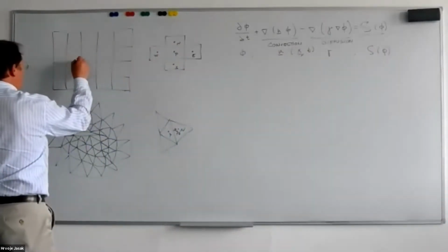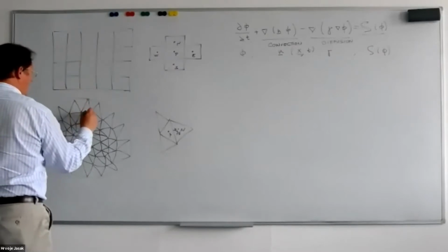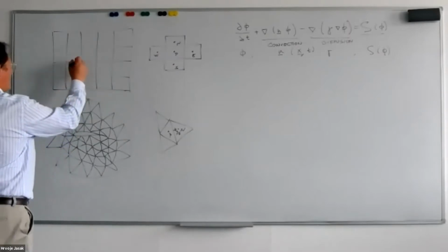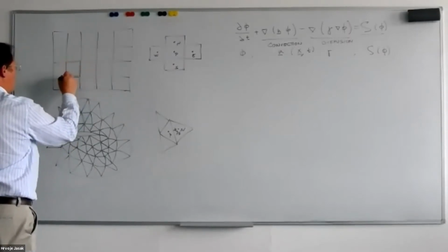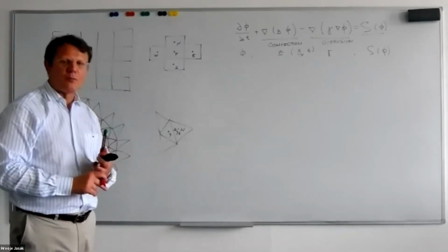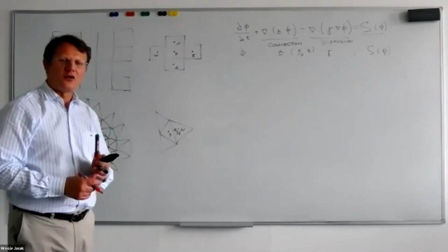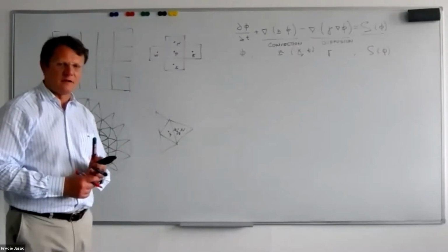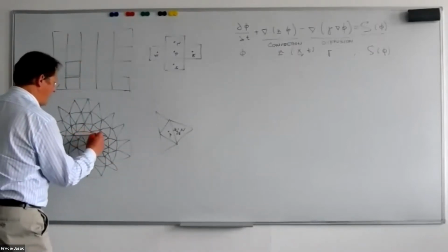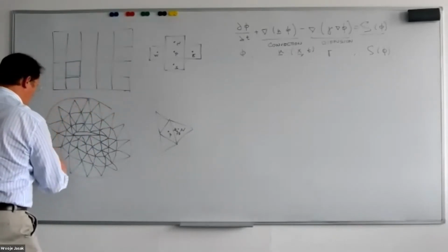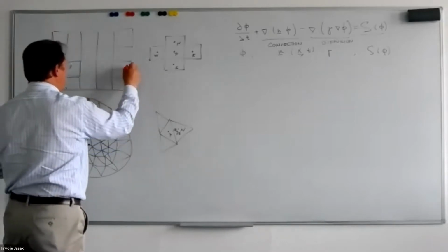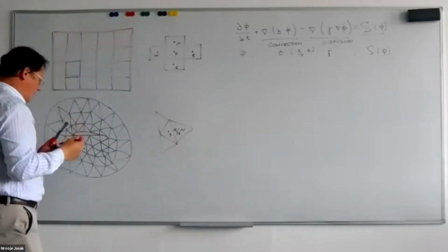For example, this one here, or that one here, where control volumes are separated from each other by internal mesh faces. Apart from the internal mesh faces, which appear between two control volumes, there is a set of faces on the outside surface of my computational domain. Here, I have the shape of my airfoil and the shape of the far field, whereas on the top, I have the outside boundary of my computational domain.